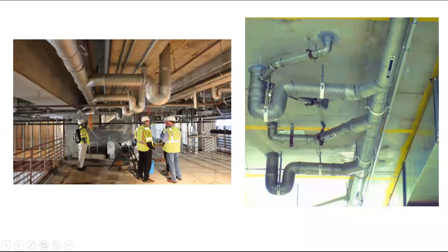The water will be there at this level, a minimum of 50 mm, stagnant for preventing the odors and insects like that only. Some of the areas are connected directly without providing the feed drop. They may have provided this drop above the floor, that's why they have not provided it in the underfloor. So like that it will be there, or pipe support, everything will be there.